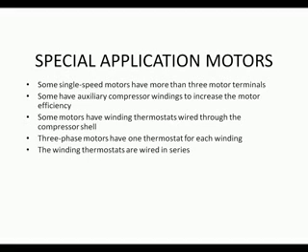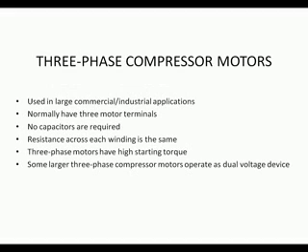Two-speed compressor motors are used to control the capacity of the compressor. Speed changes are obtained by wiring changes. The thermostat controls these wiring changes. It's considered to be two compressors in one housing. One motor may turn at 1800 RPM, the other at 3600. Two-speed compressors have more than 3 motor terminals.